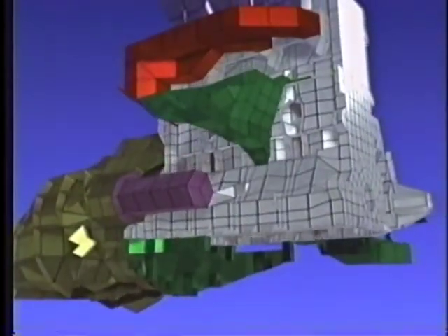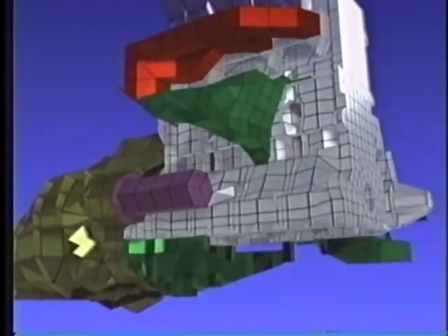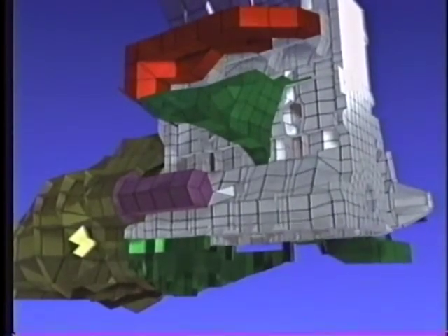The heart of the simulation is the movement of the rotating crankshaft and the excitation forces of the nonlinear oil film, shown in the next sequence, where the influence of the torsional vibrations is also clearly visible. The evaluation of crankshaft dynamics is another application of Excite.